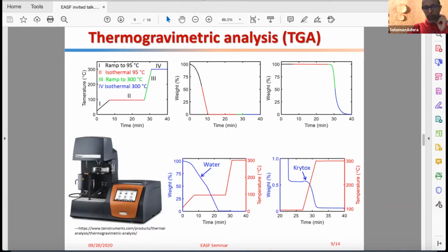And so by so doing, during the first decline here, we're able to quantify how much water we have in our mixture. And then when the second drop down occurs during the third stage, we're able to quantify how much oil is depleted by the falling droplet.